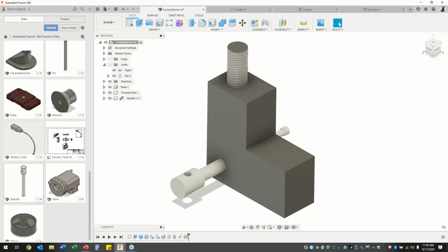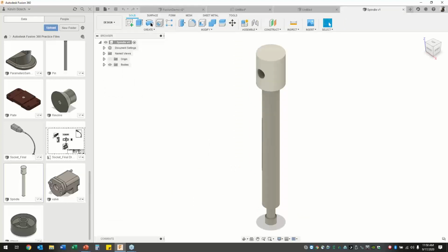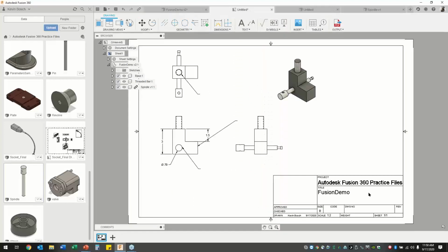Do you know where in the background the title block is to modify and make a new one, like an IDW in Inventor? Let's see here. If that's where that is, right here, just a right click, we can edit that title block. We can create a new title block, edit the properties. So they're right inside.